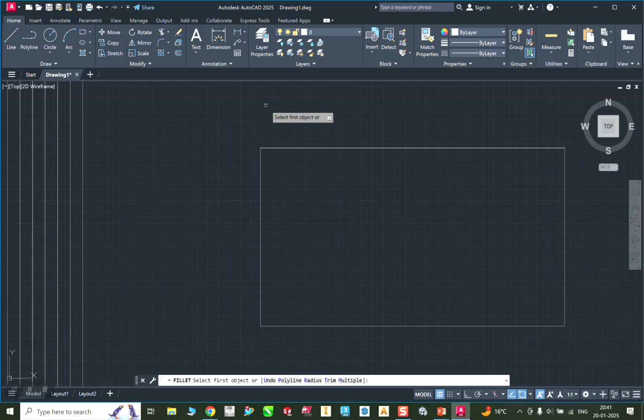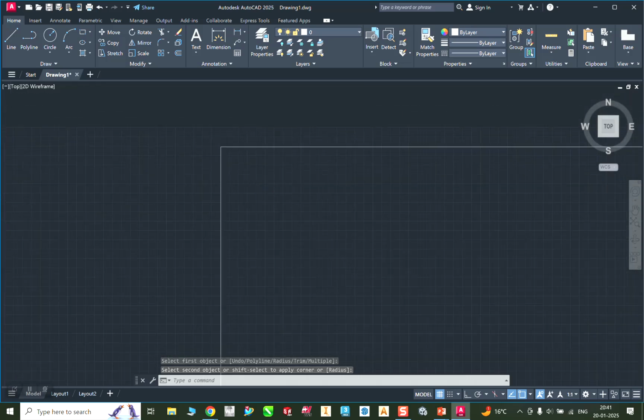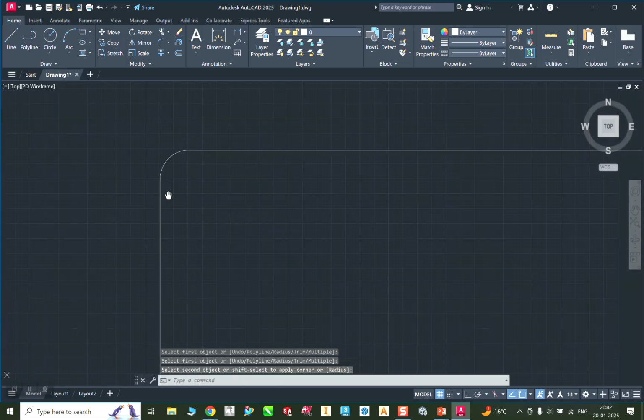If the corners are sharp, it's going to hurt you. So we need to make them round, or fillet. It is quite a very small radius. So again, I'm going to click on radius. It's going to ask you for a value. I'll say about 100, because the geometry is quite large. Just click on this, and okay, this is your round surface.